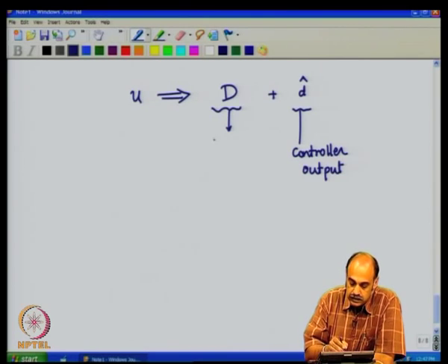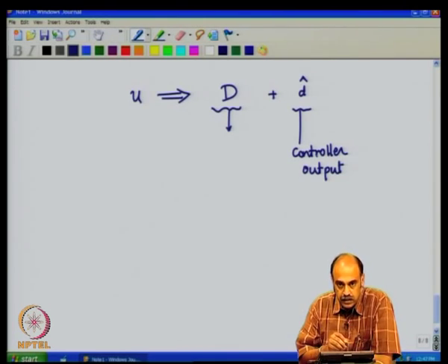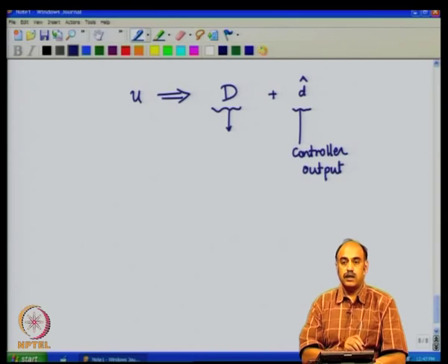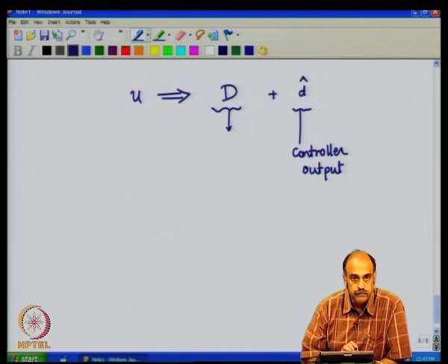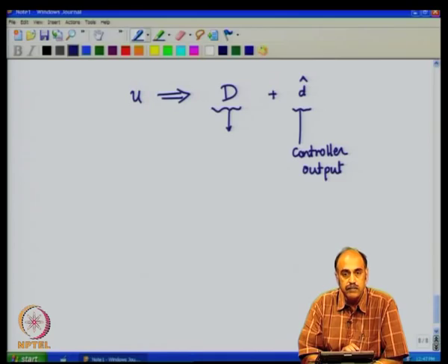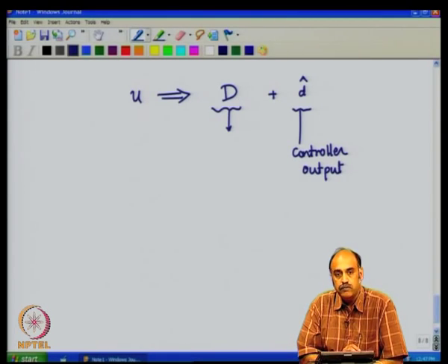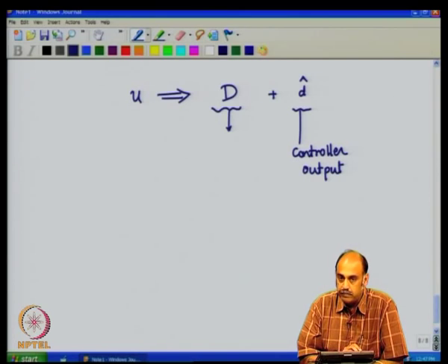So, this is the approach that we will be taking even for the DC-DC converter. Now, from this what we gain is that whatever may be the plant, linear or non-linear, the first step is to convert the plant into a linearized small signal model. So, it is this linear small signal model that we further use for developing the controller design.